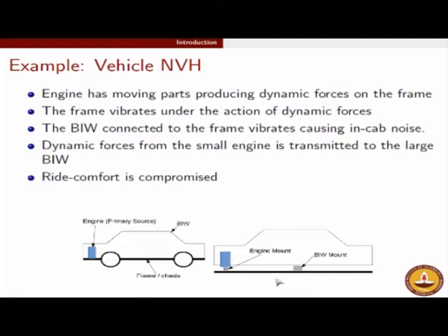As engineers, our purpose will be to make sure that minimal forces are getting transmitted to the frame, because if the forces are beyond a certain limit, firstly it can cause the frame to fail, because it cannot sustain fatigue load as much as it can sustain a static load, and also, in the automotive example, as I have demonstrated, it can cause severe issues in terms of ride comfort, which is basically dealt with in the subject of vehicle NVH.